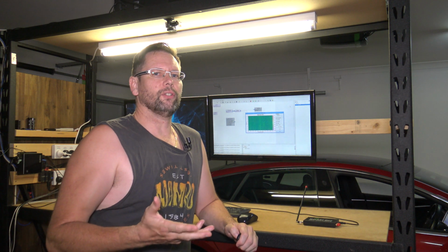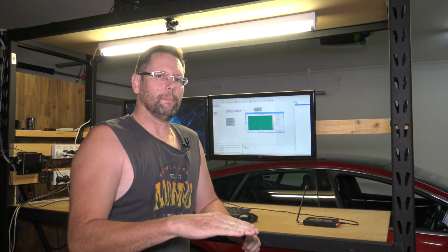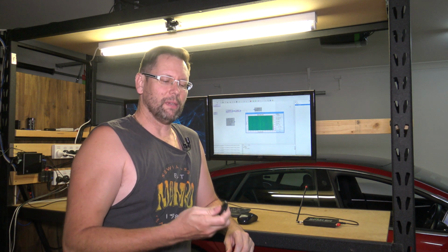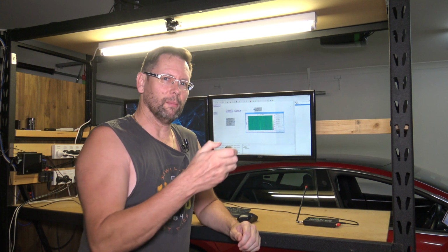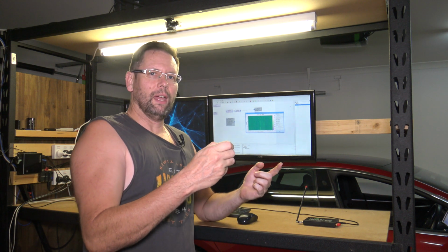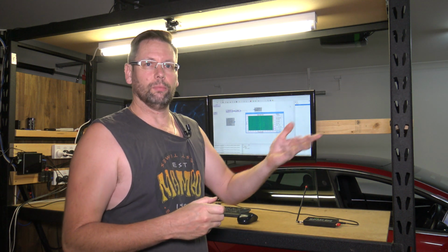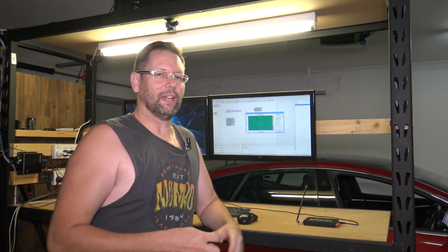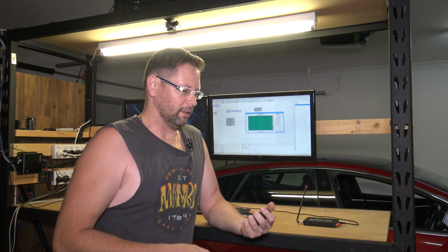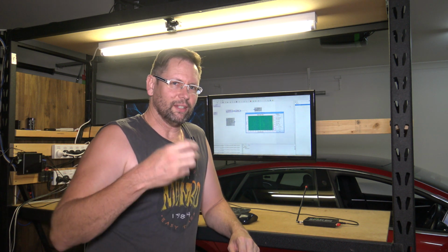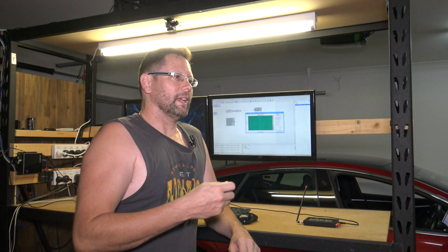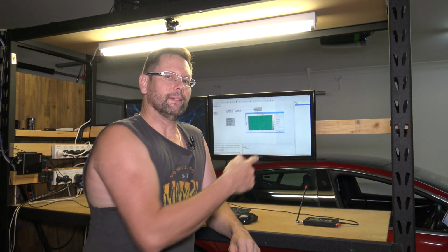So if you're having an issue where your garage door is going up and then stopping, it may be that something interrupted that signal, you know, if it didn't quite receive it properly, and it might have seen it a bit, saying, yep, let's go up, and then saw it again and said, oh, we've got to stop now. So that could be happening, or it just doesn't like a 2 second button push. But I'd say that's what's happening: if you're having trouble with your garage door detecting 2 button presses, it's probably because it transmits for 2 seconds, and if there's an interruption during that time, it'll just see it as 2 button pushes.